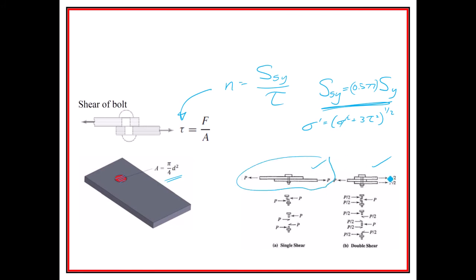And if we were to have this kind of situation, this is like the one that the equations are for in the book, but we could definitely double up the plate right here. And if we wanted to figure out what kind of area to use, we would need to do free body diagrams here and remove the plate so you could look at the bolt. This is often what's necessary if you're unsure about which area to use. Draw these little tiny figures and figure out how that's going to happen right here.